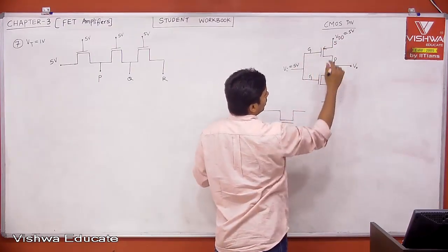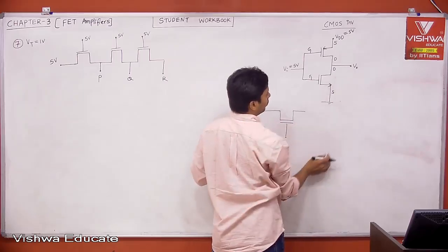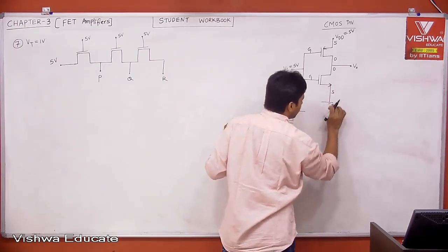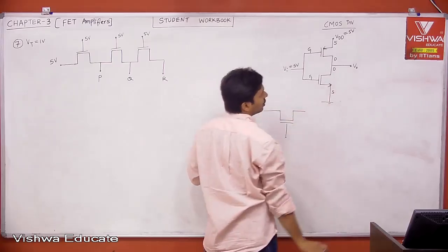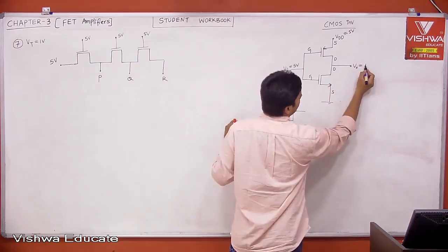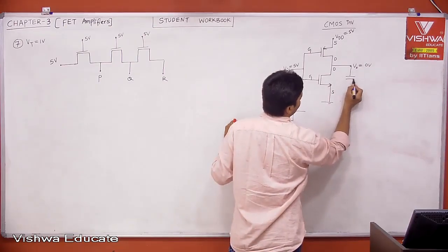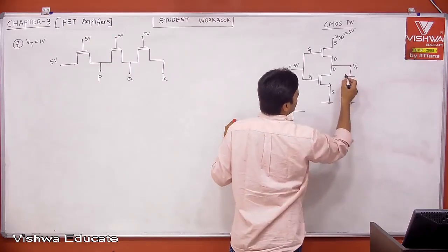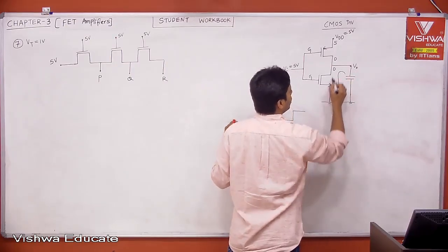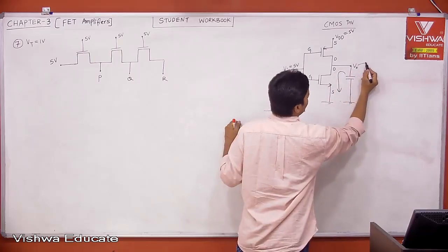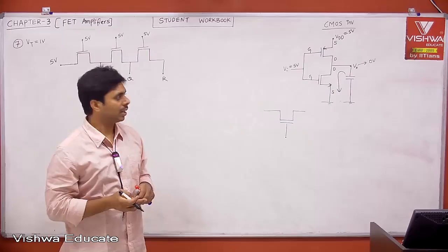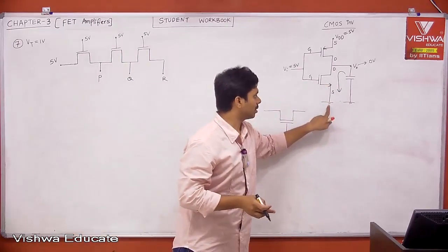This is off. Then this 0 will come here, so the 0 is going here, which means it is pulling down. Your output is going to 0. Even though the capacitor here, which is nothing but your load capacitor, was charged, it will be discharged. Therefore, your output voltage is going to 0 volt under steady state, because your capacitor is discharging.